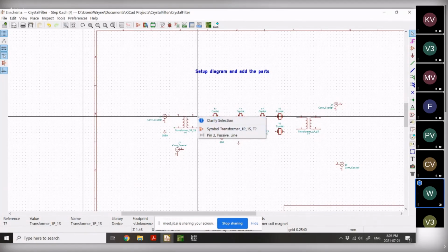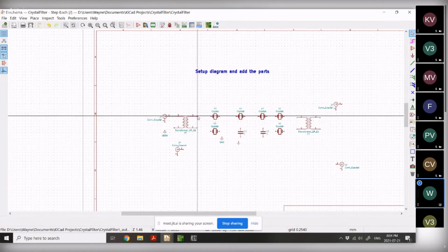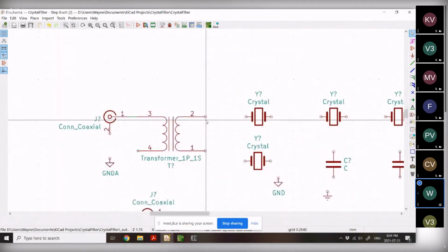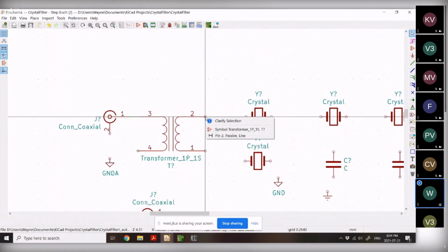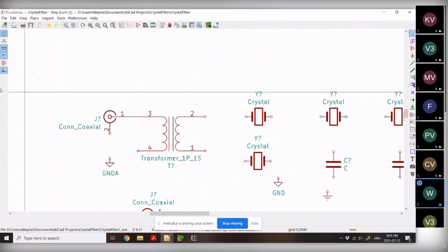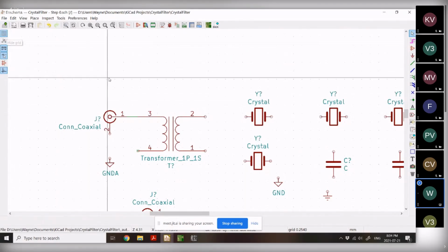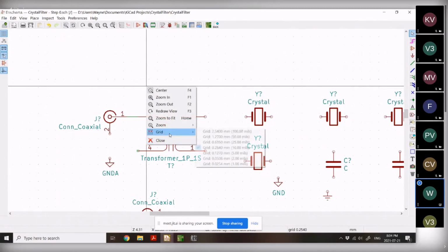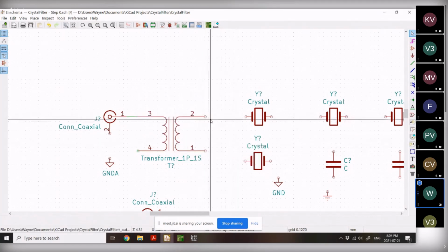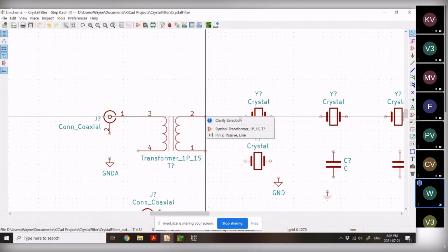And it does this stuff. It's doing this for a reason. It's having trouble finding the spot. Generally speaking, you have to bring it really close to you before you can do that. And there's another reason it's doing this, which I learned kind of recently, and it has to do with the size of the grid. What's going on is it can't find the end of this thing for some stupid reason. If I go to the grid here and just show you what you do with the grid. The grid is set to 2.2.4. I just make it smaller, and maybe it'll work.